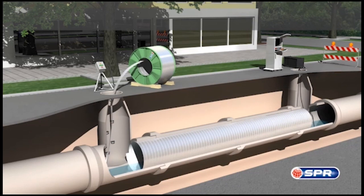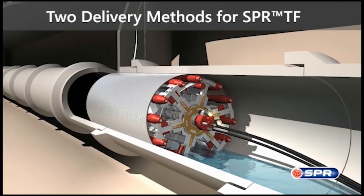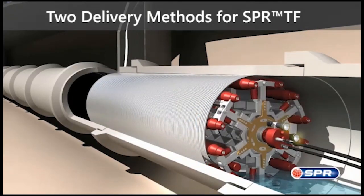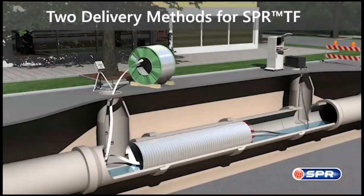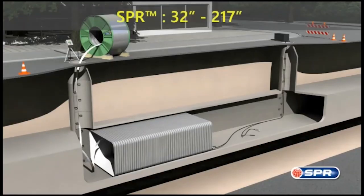And now we have a secondary type of equipment here installing our liners. But again, we look at this on a project-by-project basis. This is the RO equipment within this family. And as you can see, the spring-loaded arms are rotating around the inside of the host pipe and tightly fitting the liner against the inside of the host pipe. And again, we can install in live flow, as you can see from the demonstration.